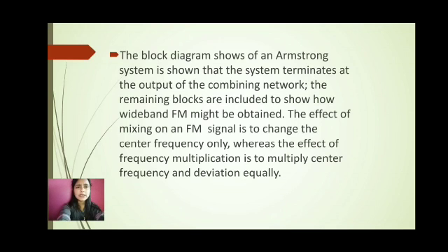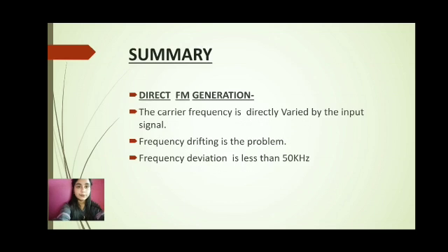The effect of mixing on an FM signal is to change the center frequency only, whereas the effect of frequency multiplication is to multiply the center frequency and deviation equally.